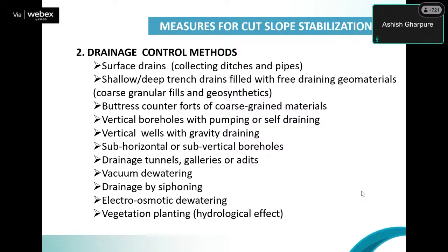I would put 80% weightage on drainage control. So 80% of solutions may come from drainage control alone, whereas the cost of drainage control may be only 20% of overall cost, and vice versa, that 20% solution may come from 80% of the cost of all the rest of the solutions. So can't emphasize enough about drainage control measures.